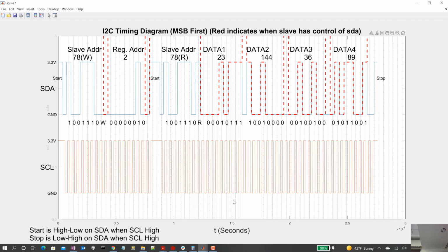And then the way that changes with I2C, when we want to just write to the device, we don't need to do the additional slave address. We just say, hey, I want to write to this, and then this would of course be a little different, and you would write out the data that you wanted to. And most devices auto increment, but you'll see today a chip that I am looking at, maybe it looks like it doesn't auto increment. So you got to look at your different chips, read the data sheet to find out what's going on with each of your chips.